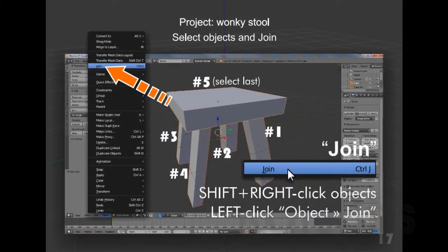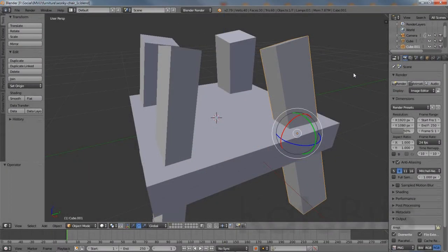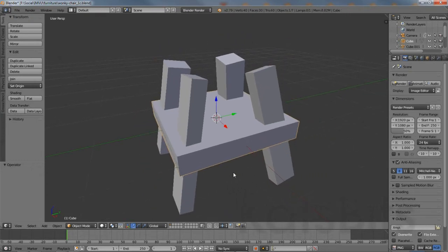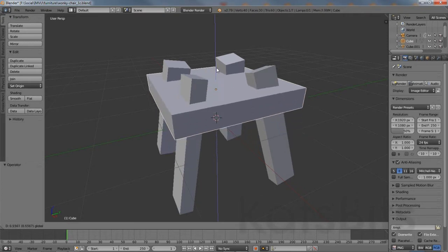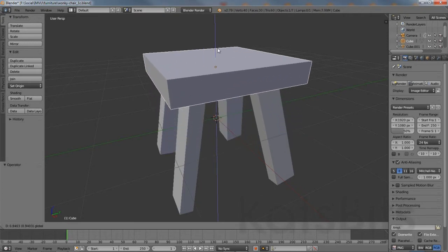After these basic manipulations are done, the objects can be joined. With the legs tilted, left-click the Translate widget button and then right-click the seat section. Use Ctrl or middle mouse drag to zoom out if needed. Then left-click drag the blue widget handle upwards so the mesh sits atop the legs.